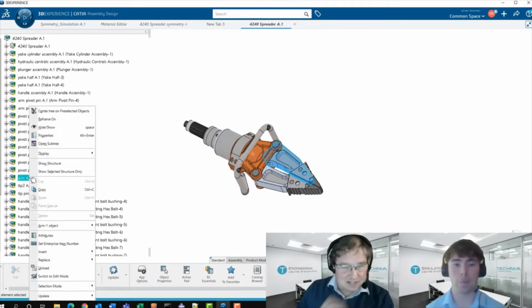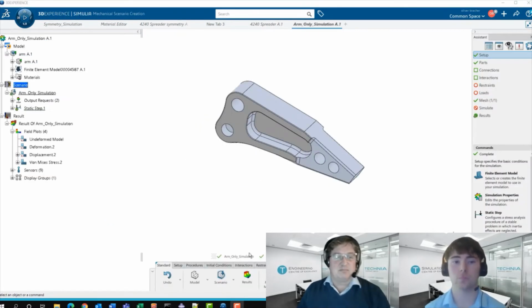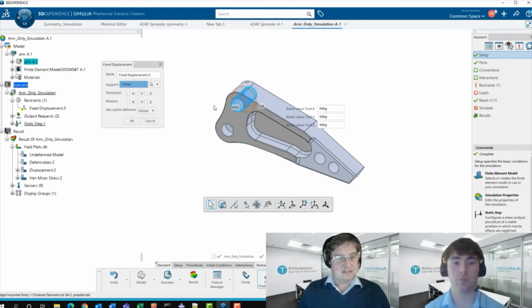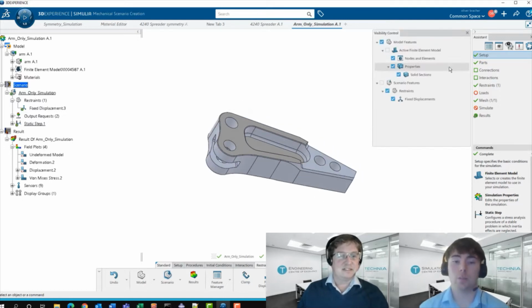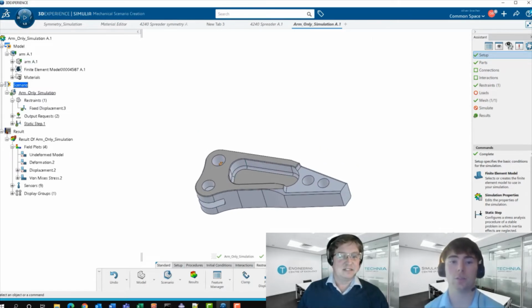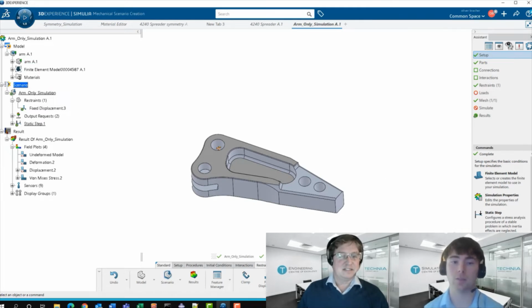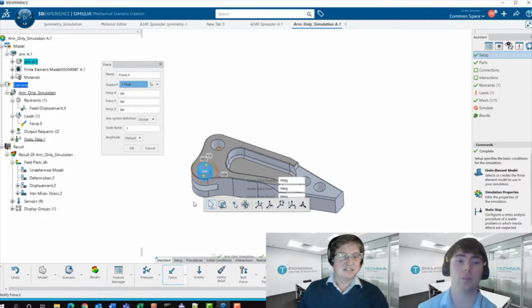Okay, that makes sense. An area of interest is the arm and whether it's going to be within the specified deflection and deformation limits. So if the loads are known to us, we can simulate the arm individually just by using boundary conditions and constraints. For the arm, we could use a constraint to represent the pin which the arm is rotating about. This would fix the nodes on the inner surface of that hole in the X, Y, and Z planes, but allow for axial rotation, just like a real pin.